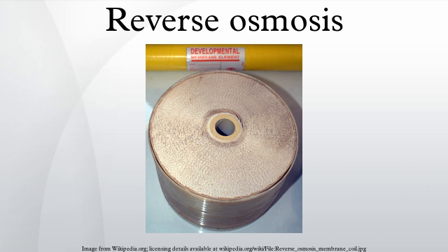Remineralization and pH adjustment: the desalinated water is stabilized to protect downstream pipelines and storages, usually by adding lime or caustic to prevent corrosion of concrete lined surfaces. Liming material is used to adjust pH between 6.8 and 8.1 to meet the potable water specifications, primarily for effective disinfection and for corrosion control. Remineralization may be needed to replace minerals removed from the water by desalination. Although this process has proved to be costly and not very convenient if it is intended to meet mineral demand by humans and plants. The very same mineral demand that freshwater sources provided previously.